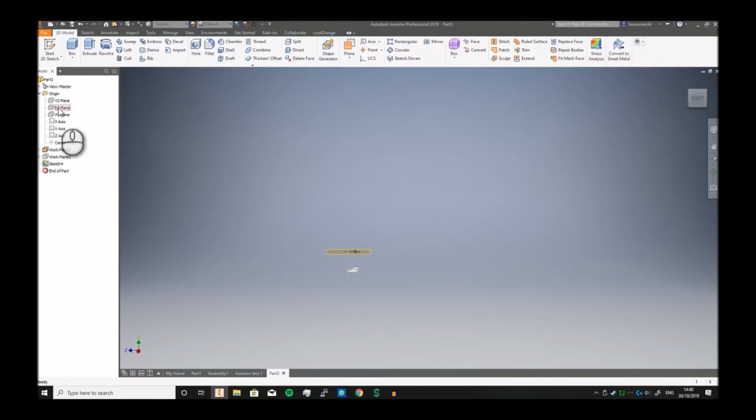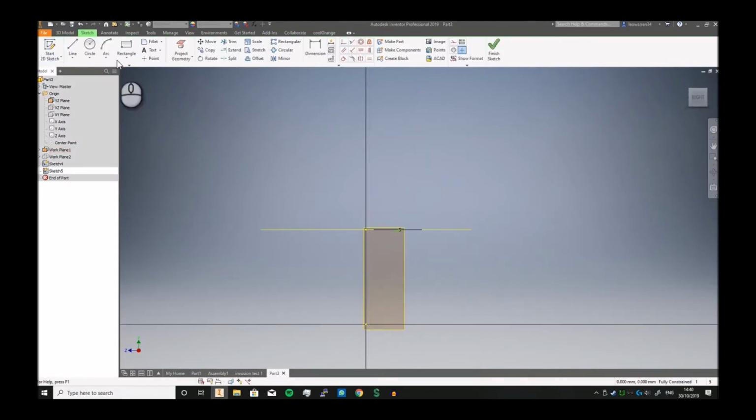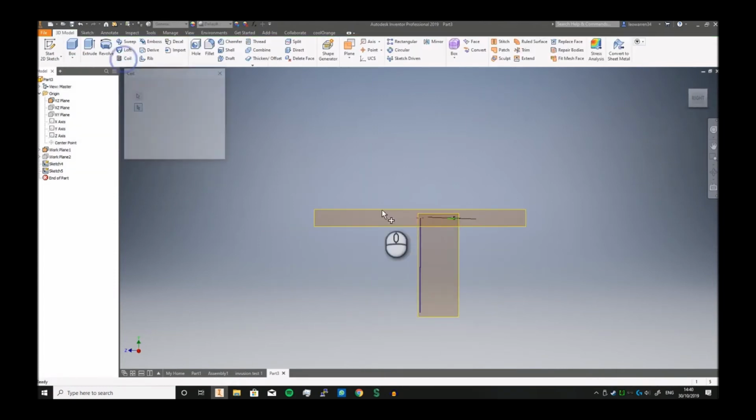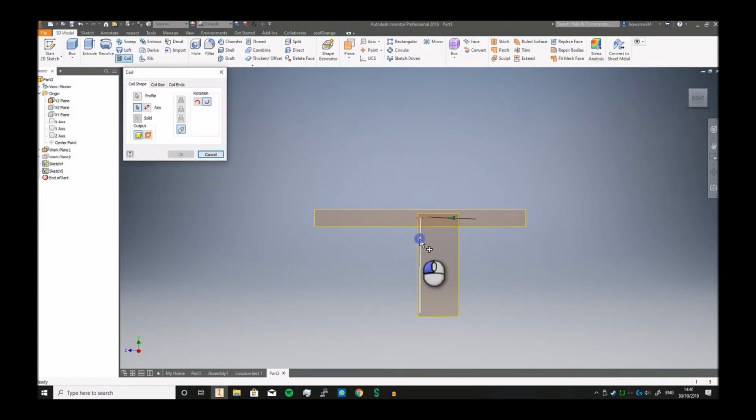and then we actually go onto the right base. And we just start sketch on here. What I can essentially do is select, well, here's a path, click OK, click finish, click coil. That could be the axis. That's what it says, it's taken the profile and it's now coiling it around here, but what you need to then do is, you see I can flip it using the axis button.